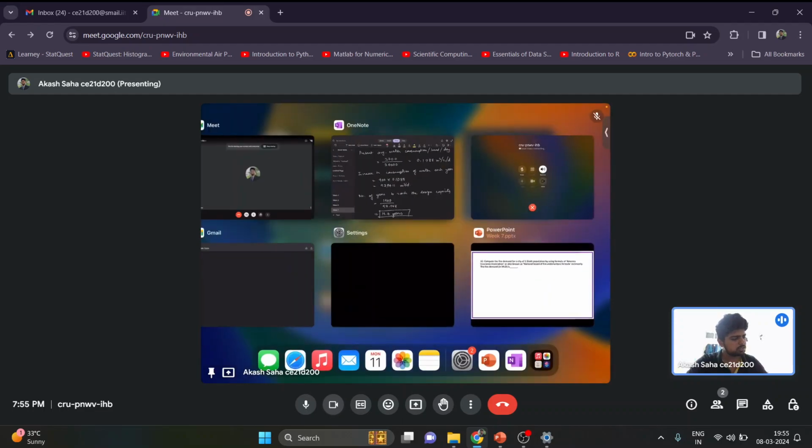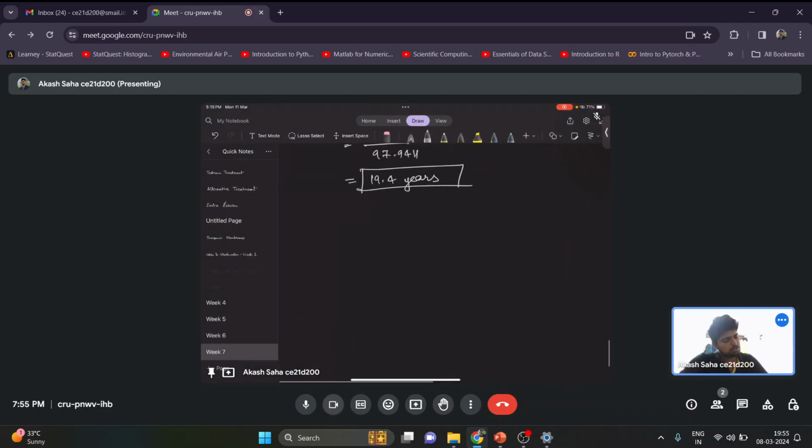You will see the formula for this. So the formula is given as Q in liters per minute is given as 4637 under root P into 1 minus 0.01 under root P. Again the discharge here empirically is found out to be in liters per minute, and the P is the population in thousands. So again the same funda, in thousands you have to find out. It is given for 1.5 lakhs, so in thousands it will be 150.